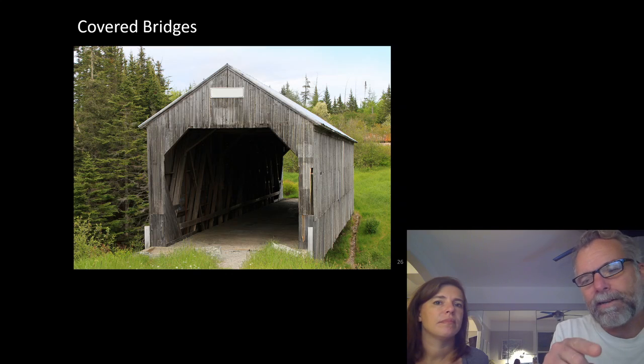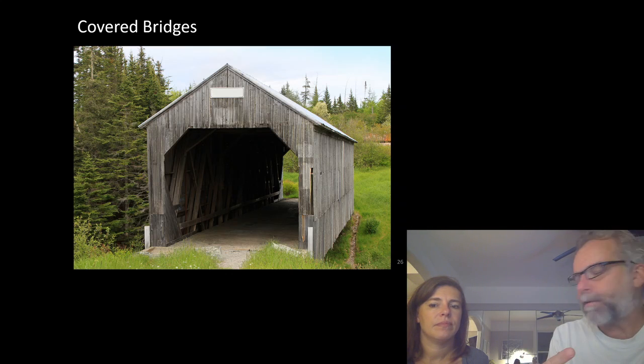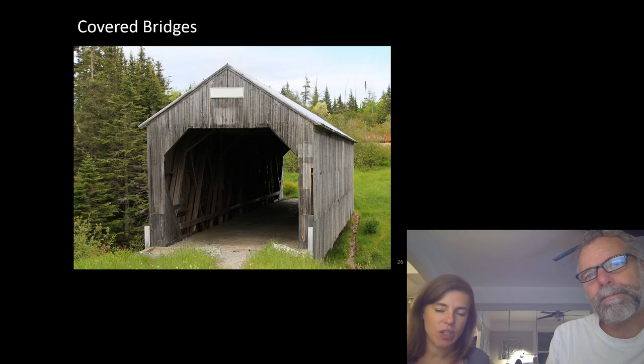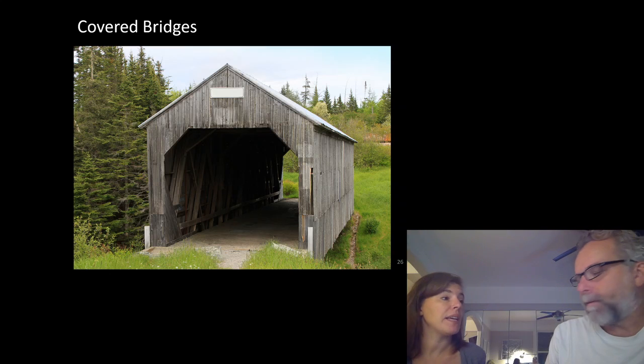But if we look at the connection details and think about the fact that they're built out of wood, this is a highly pragmatic truss, which is why they are so common. Every element is smartly placed in the right orientation, doing a very specific job to maximize every little bit of material and make it easy to build.